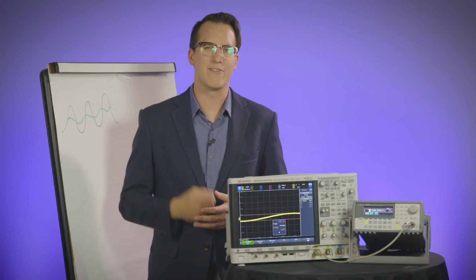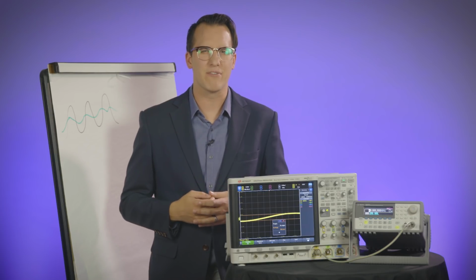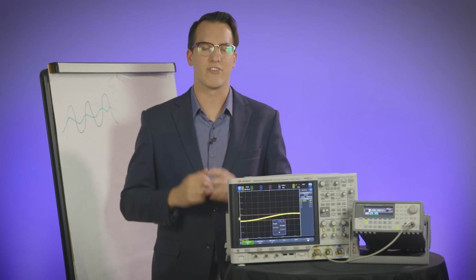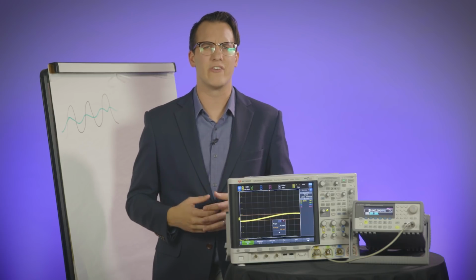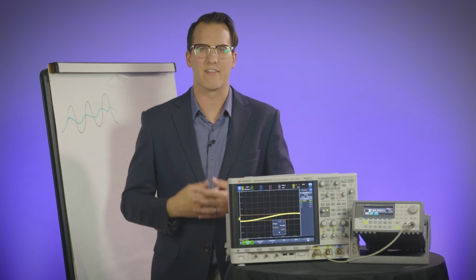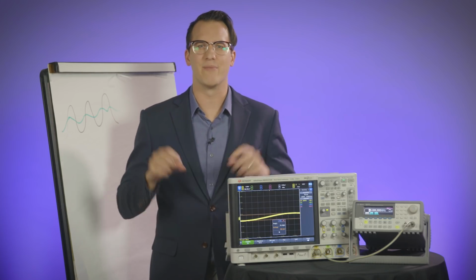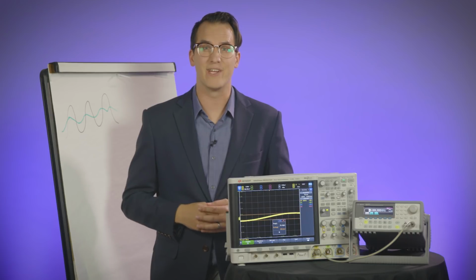So if you're picking out a function generator, think about what types of signals you want to generate, not just the max bandwidth. A general rule of thumb for square waves is that you need a generator with at least 3 times the max bandwidth of your square wave frequency. You can also use this knowledge to push some of the specs of your scope, which is a topic for an upcoming video. But if you don't want to wait for that video, there's a blog version, there's a link for that in the video description.